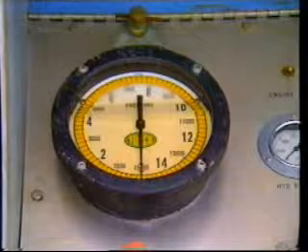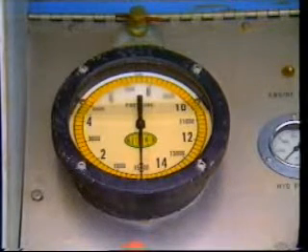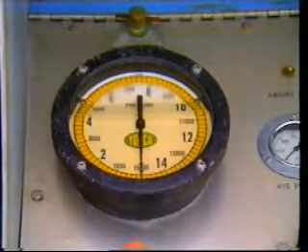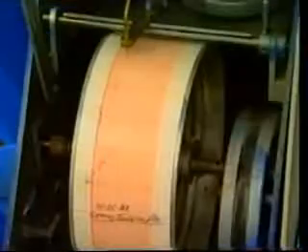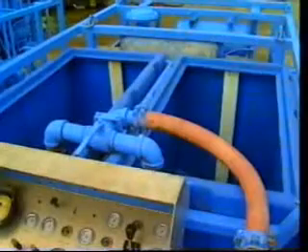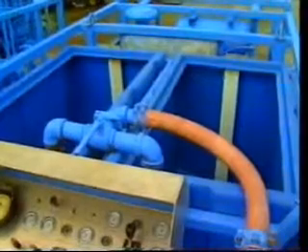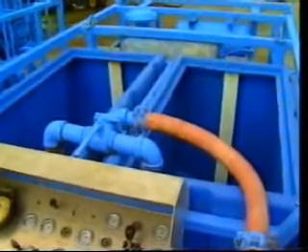Treating pressure is closely watched to ensure that the pressures remain within design parameters. Treating pressure and rate are permanently recorded. The service company must also closely monitor the displacement tanks, in this case 2 calibrated 10-barrel tanks which hold the sand-laden fluid pumped from the blender.